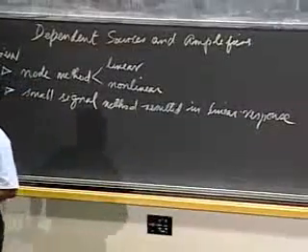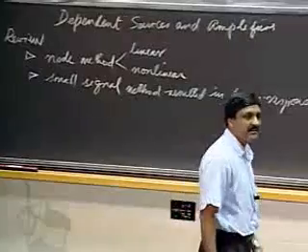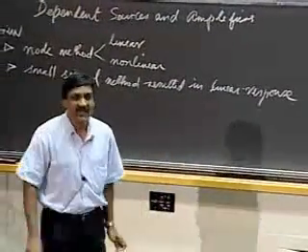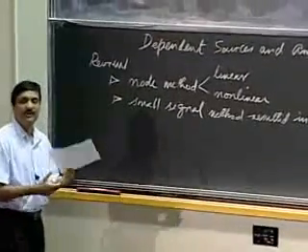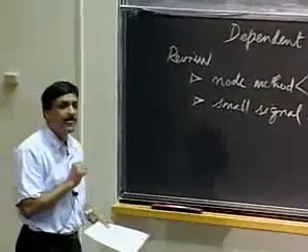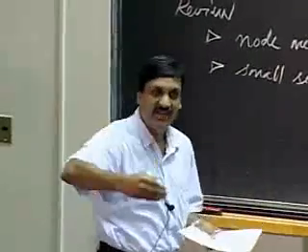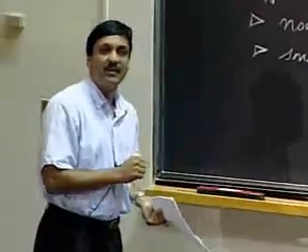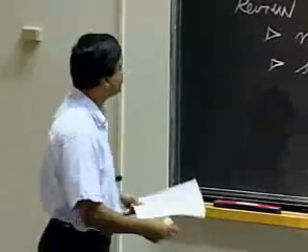And as an example, I showed you how I could take a highly nonlinear device like the garage door opener LED and using that build a pretty nice transmitter that would transmit music, and as long as they kept the signal small and operated the device in a region where its transfer curve was relatively smooth, and I biased or set the operating point appropriately, I would get a linear small signal response. Okay.